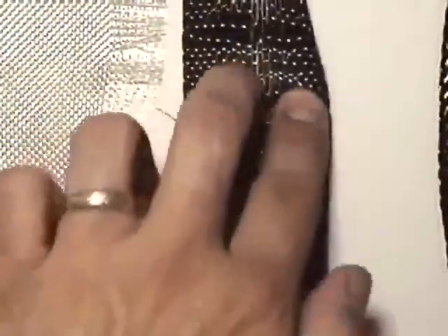If you look at this piece of carbon, let me back out just a hair. All the carbon fiber is running in this direction, so 100% of the carbon fibers are going lengthwise on the tape. And there are just little white threads of fiberglass in here, and those aren't really for strength. Those are just to hold the tape together while you're laying it up. This one really only has strength in one direction. If we tried to lay it up and wanted strength across this way, it's not going to be very good for that.